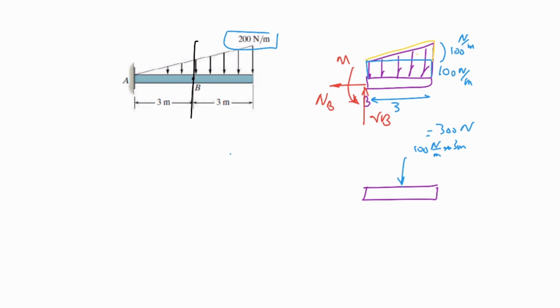The same story here, but we have a triangle. The triangle story is a little bit different. When we have a triangle and distributed load like this, let's name this guy A and B. We replace this force with a single force at 1/3 of the length, meaning that it would be the area of this, which is AB over 2.